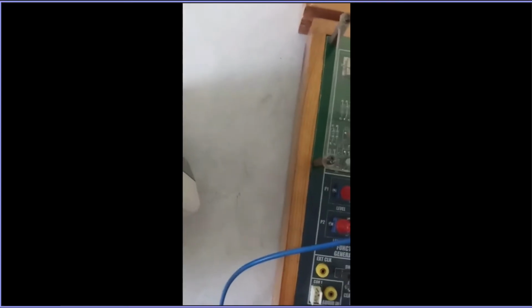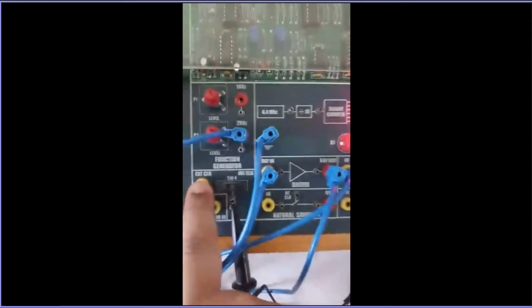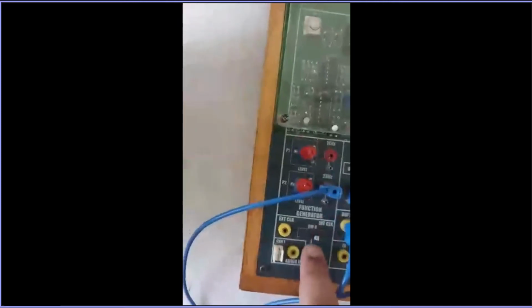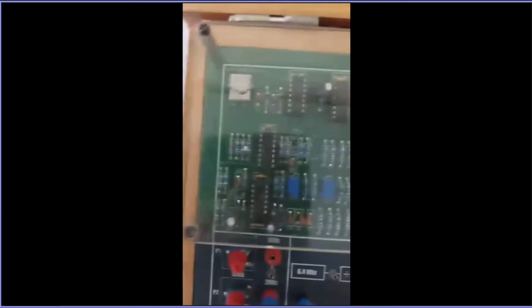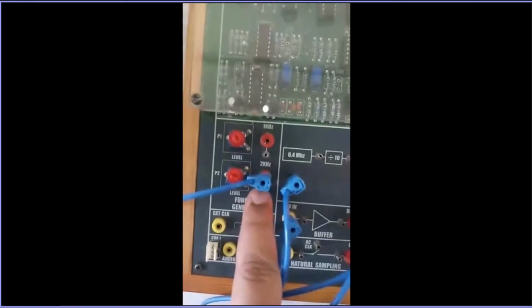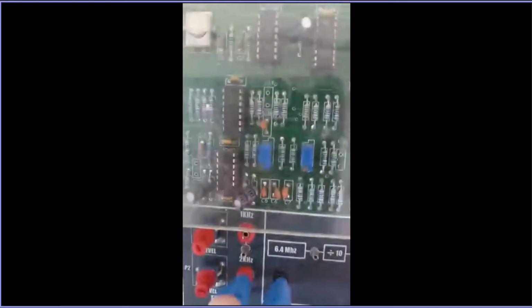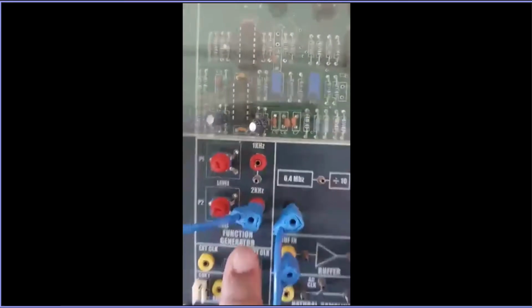Okay. So now we should also check the function generator setup value, right? And you can see this is the clock value we have set. There is an internal clock and an external clock. This is the external clock, this is the internal clock. So we have provided the internal clock. You can see the switch. The internal clock value is there, right? And we have provided input of 2 kilohertz. You can see here 2 kilohertz, and here it is 1 kilohertz. It is written here. I guess it is visible. 1 kilohertz and 2 kilohertz. So we have provided input of 2 kilohertz, right?